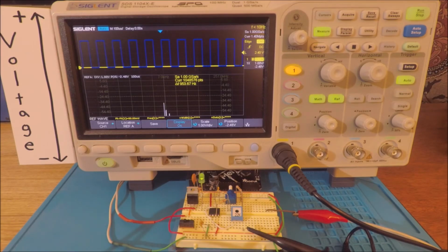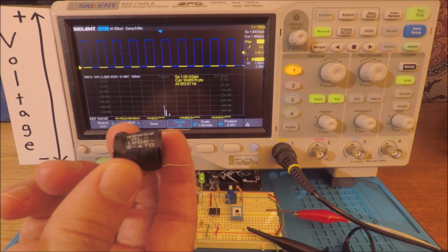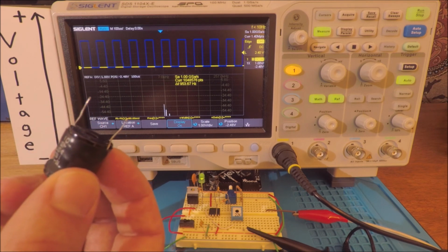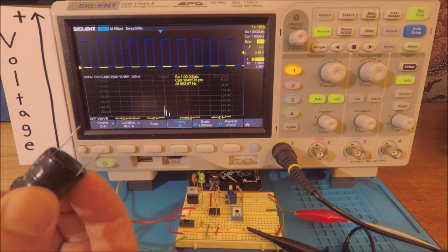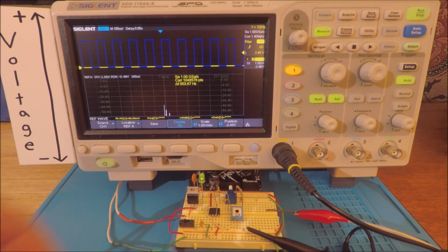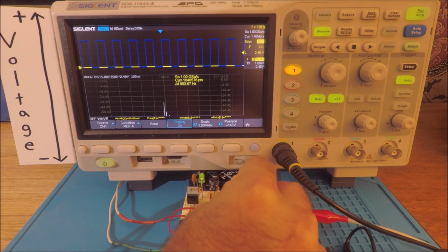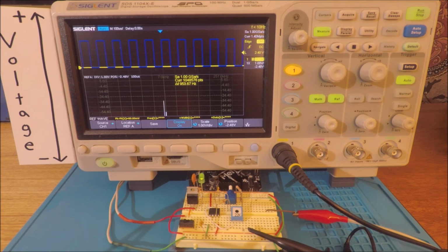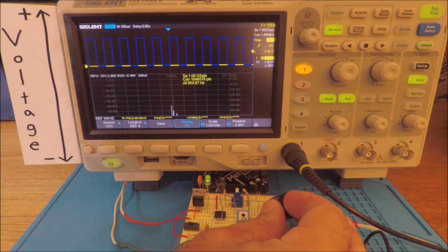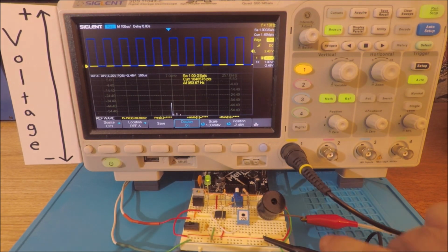In fact, when we go to construct this circuit, we only need to use two components. Here's the inductor, which happens to be a 470 microhenry inductor, but it's also going to have resistance associated with it. And if you measure the resistance across both terminals, this particular one is 1.37 ohms. So this one component is going to operate as both the resistor and the inductor in the RLC filter. We can combine that with the previously used 1 microfarad capacitor. We'll bring in the inductor and connect our scope probe.